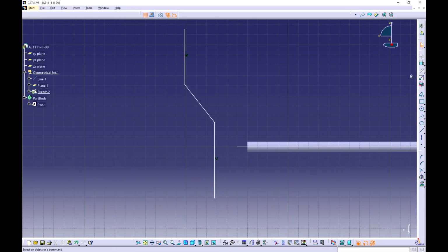So now we make constraints. Select the constraint tool. We need constraints for this one. The distance between this point here and the middle axis, and also the lower point and the middle axis. And we also need a constraint for the thickness, so from the distance from this point to this line here. So select both the line and the point here, or both lines, never mind what you select.